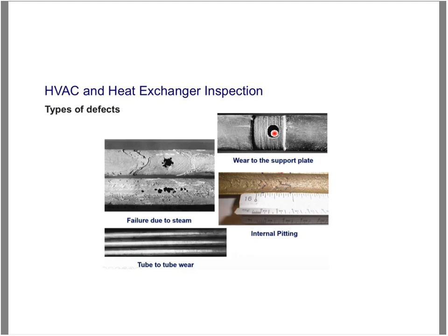Well, we have this pit that was created. Now, pits can also happen on the inside. Here we have internal pitting. Same thing. If you're using a very corrosive material inside the tube, pitting could occur. And once you start getting some pits, you get more pits, and before you know it, you have a lot of pits. So you have wall loss, you have pits, and the problem with pits is they can actually sometimes lead to holes.